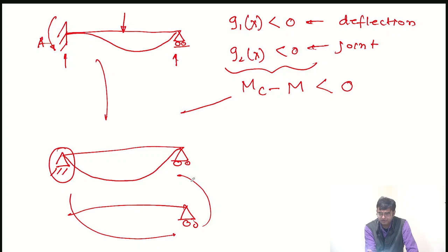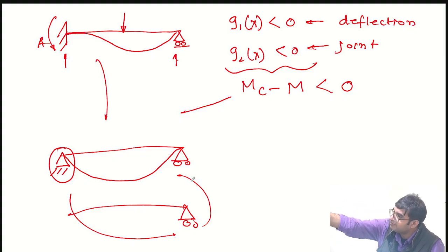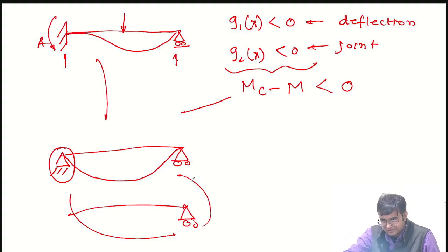So redundancy is important. You will try to make a structure, system, or component, if possible, in some cases, redundant, so that you have a backup. When it goes from that state to this, you will feel more deformation. That is also an indicator for calling for maintenance, which means it has not failed, but it is moving towards failing. Why not maintain it? So it is also a signal towards that. Maintenance is an integral part of reliability.